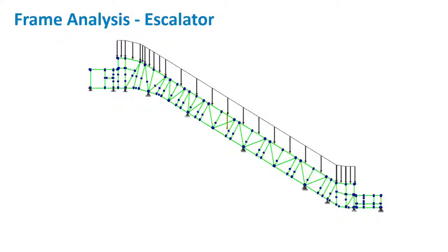They moved from frame design to frame analysis, and automatically the model turns from just the lines or the beams to a beam FEA model where you have beam segments and rigid links. All the black marks here are rigid links that connect the beam ends, as the beams don't physically meet, they end a bit away from each other.